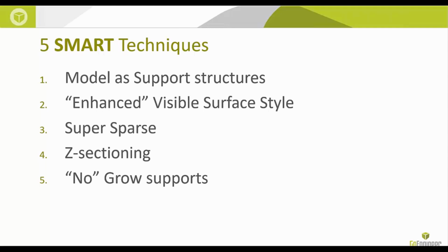The final technique we're going to highlight is the no-grow supports. I'm sure you've seen this before, where you have maybe one little hole or one little feature at the top of the part, and suddenly the support for that feature or hole grows beyond its own extent, and now we have these huge support fingers cascading all the way back down to the base. We can use the no-grow supports and the support parameters to eliminate that, keep the supports contained to their boundary, and drop the time off.